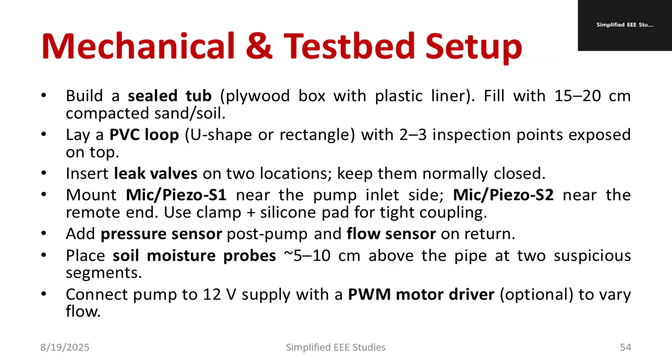First case, no leak. Second case, open the valve. Identify at least 2 or 3 locations. Keep them normally closed. Then if you want to create the fault, just open the valve, which means it will act as a hole, right? Mount the mic or piezo S1 near the pump inlet, then mic or piezo S2 near the remote end, to identify where the fault has occurred.